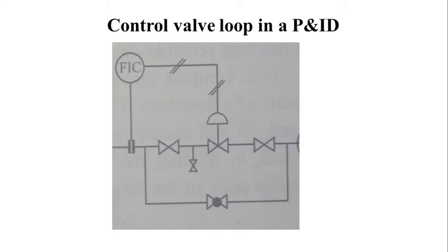In the case of the valves that you see here, one is a bleeder valve which is perpendicular to the main line. The two are isolation valves. These are gate valves to isolate the valve. In most cases, your control valve physical size would be one size smaller than the line size. The line size, normally covered later in one of your classes, is based on the pressure drop per unit length which is affordable in this particular service.